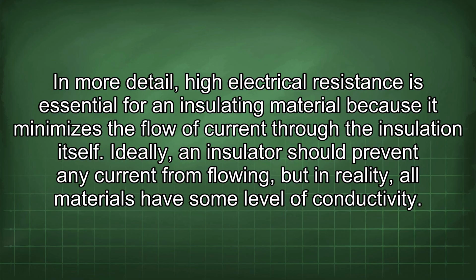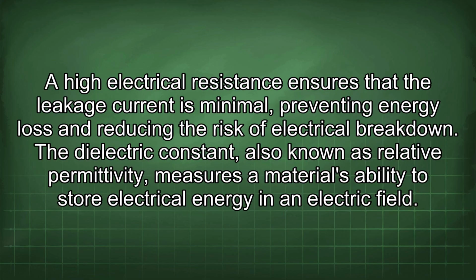In more detail, high electrical resistance is essential for an insulating material because it minimizes the flow of current through the insulation itself. Ideally, an insulator should prevent any current from flowing, but in reality, all materials have some level of conductivity. A high electrical resistance ensures that the leakage current is minimal, preventing energy loss and reducing the risk of electrical breakdown.